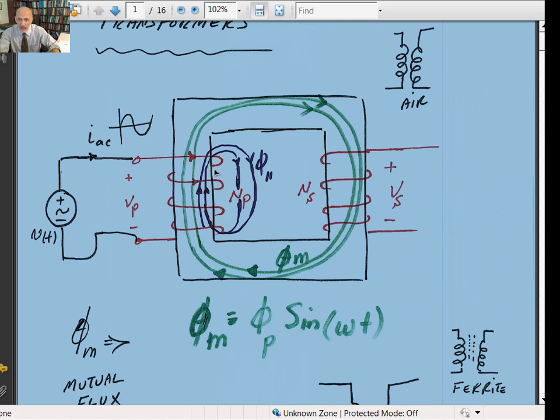The way the inductance works here, this V sub P is very close to V sub T. Otherwise, when there is nothing hooked up to the secondary of the transformer, there is no current flow in the secondary, so the primary current ideally should be zero. But you have less than 3 or 4% of the rated current flowing just to set up the magnetic field. That's the energy you have to put in to set up the magnetic field, so you'll be able to transfer that energy. So this V sub P here is very close to V sub T if there's nothing hooked up to it.